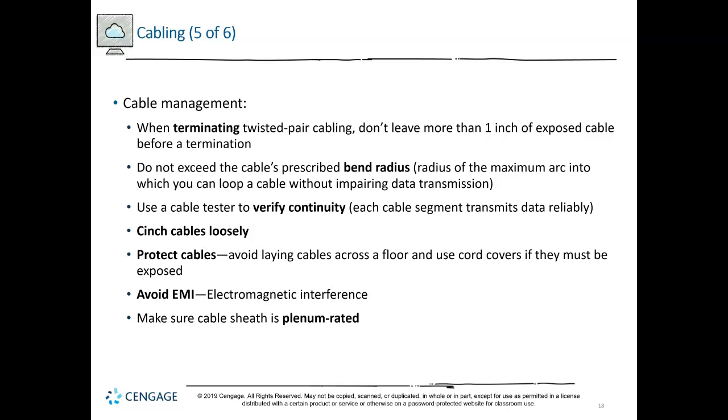Other things you can do. We've all seen those people that go nuts with a stapler and there's a cable and they're stapling it 37 times in a foot. Well, that can actually lead to some really bad things. So we typically want correct equipment to hang it with. And you want to not have those cables pushed down where they're squishing into the jacket. So we don't want to lay them across the floor or somewhere they're going to get worn.